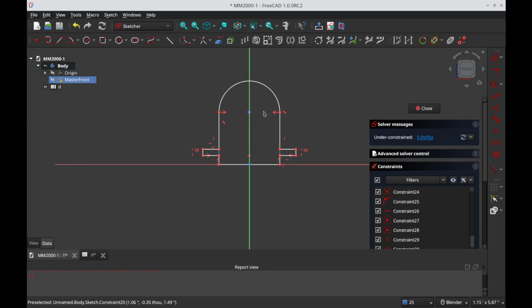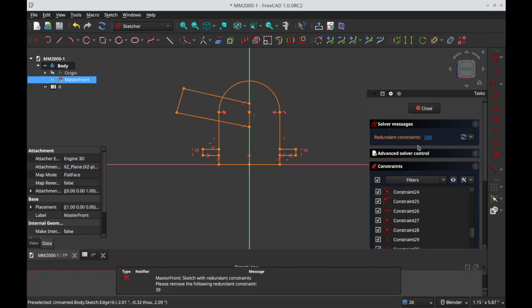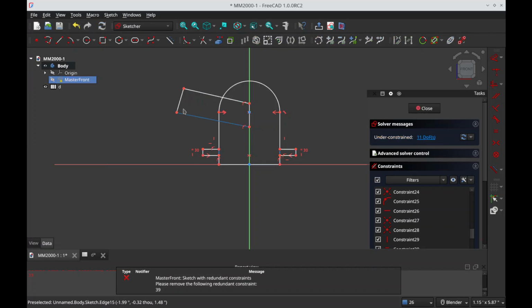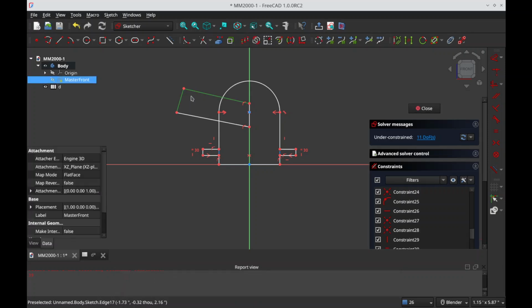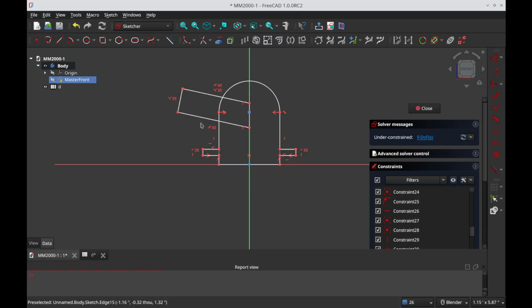We could also use the pipe, and the pipe is going to be drawn, I'm going to draw it from the center, bring it out, come back, and bring it down here. Remove redundant constraints, because that multi-line polyline does not actually remove constraints. There might be a way to fix that. But let's do a normal constraint here and a parallel constraint here. I don't know if there's a particular best practice for whether both of these should just be normal, or one normal, one parallel, or maybe it doesn't matter.